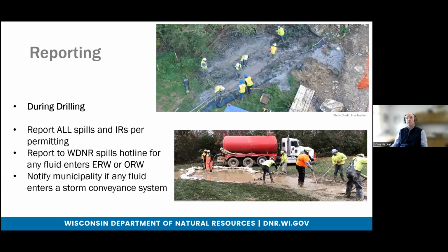And the last step would be reporting during the construction process. If requested by the DNR, you'd need to provide regular status reports on the following items: the HDD drilling status throughout the bore and pullback process, and any spills and inadvertent releases. You have to report any significant fluid losses or gains throughout the drilling process, and you must report the volume of any fluid that would be captured during response and cleanup of an IR.